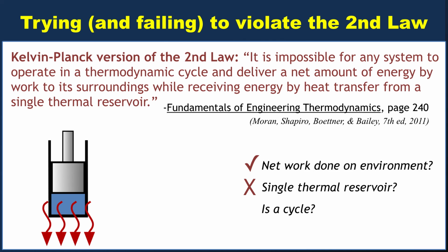So we cheated a little bit because we tried to use the same reservoir both to transfer heat to the piston and to take it away. That will work for one of those two processes, but not for both, right? You can imagine if you heated the piston up so much using your reservoir, there's no way you're going to be able to cool it off using the same reservoir. The reservoir is either at or above the temperature of the stuff in your piston. It doesn't want to transfer heat away from the piston, it wants to transfer heat to it. Likewise, if you had a cooler reservoir, well, the first process wouldn't have worked. You wouldn't have been able to heat it up in the first place.